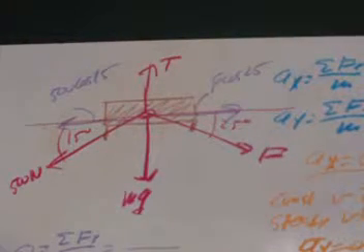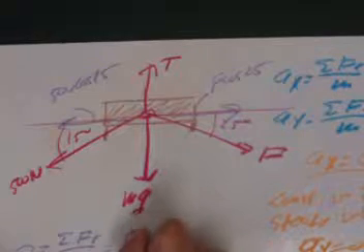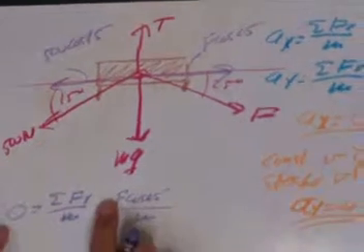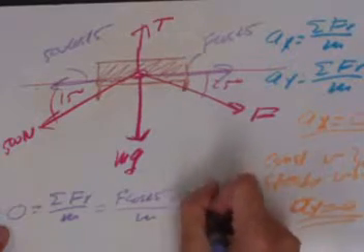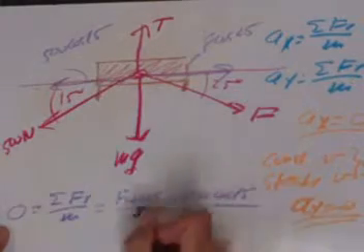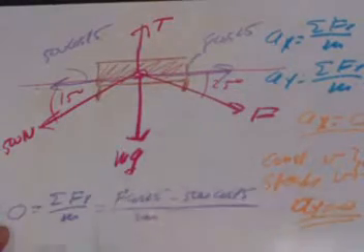So there's two x components like that. What we have then is an F times the cosine of 25, and I'm going to call this positive because it's pointing to the right, and we also have a minus 500 times the cosine of 15. I'm calling that negative because it points off to the left. That's the way the Cartesian coordinate system works, and that's my sign convention.